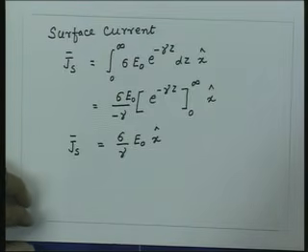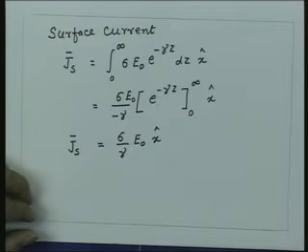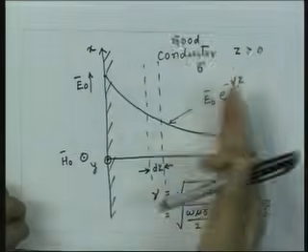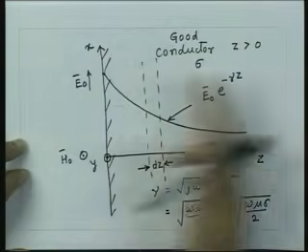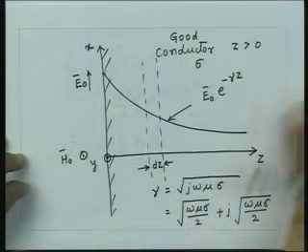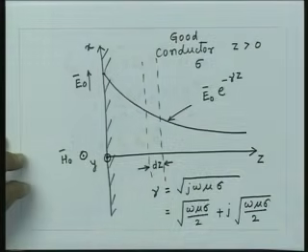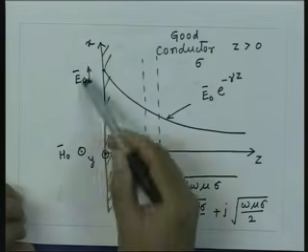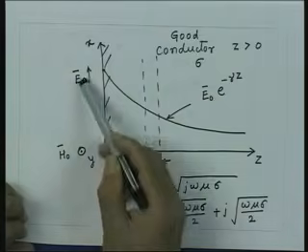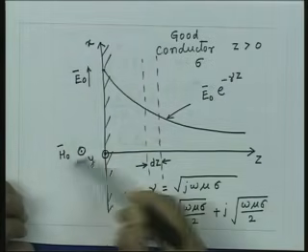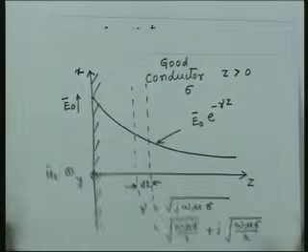So, let us see, since I have the electric field on the surface which is E0 and the magnetic field is H0 on the surface here, if I go inside this, this is giving me a wave which is travelling inwards in the z direction, and this again is a transverse electromagnetic wave because this medium is unbound in this direction. So, your E0 and H0 must satisfy the relation that the ratio of the magnitudes of E and H should be equal to the intrinsic impedance of the medium.